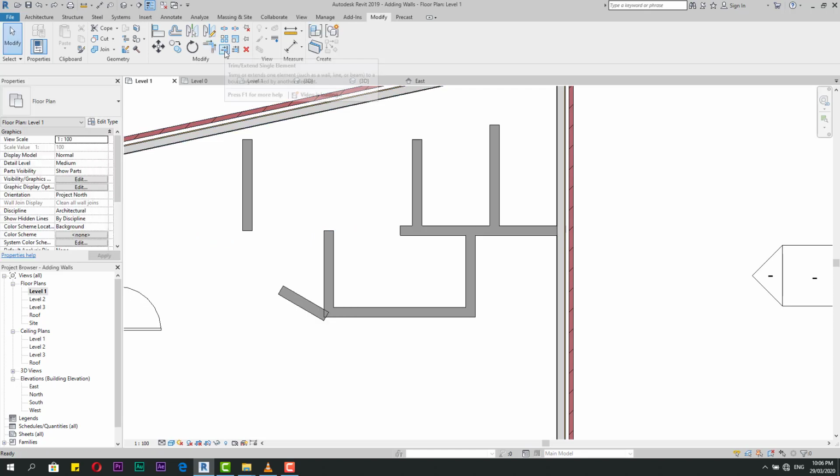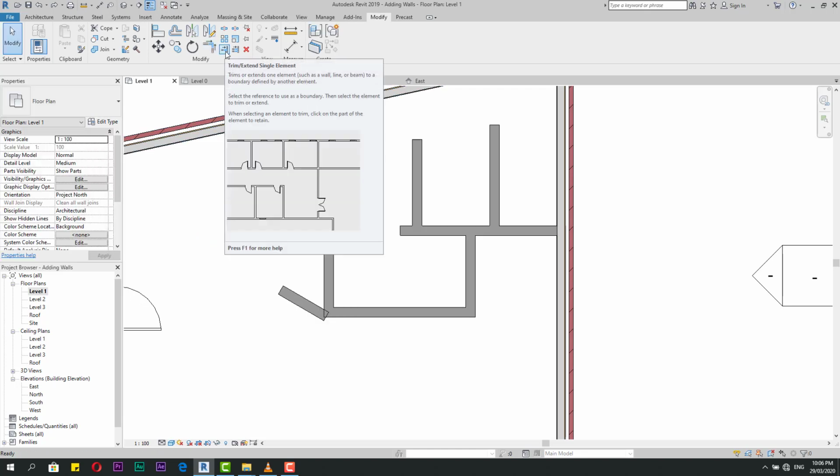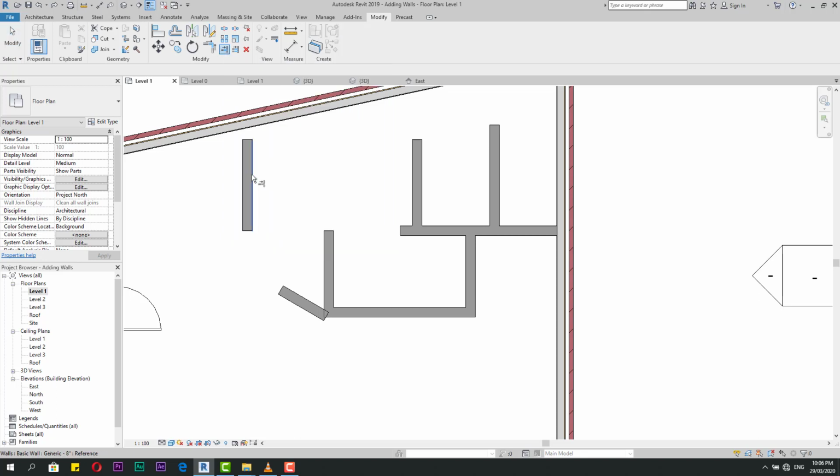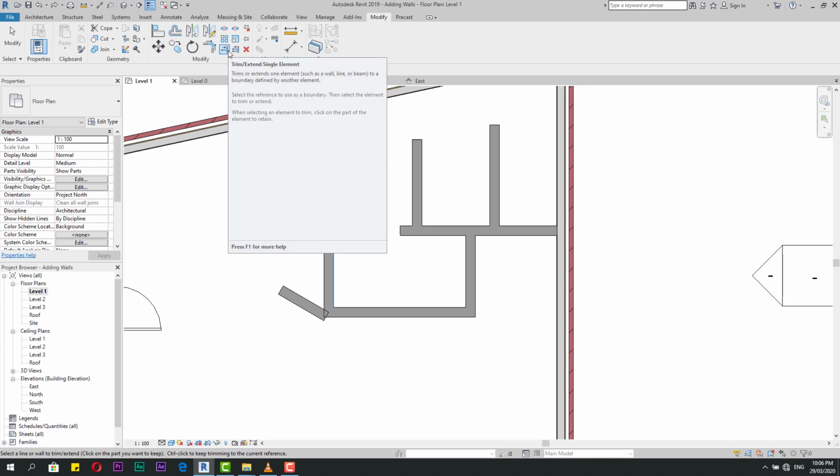Okay, the other thing we need to speak about is extend or trim. Just I click here. If I select this one as the reference and click here, take care what happens. It's similar to this corner, okay? With trim, I can make a reference for this. But the corner can make this shape, while trim cannot make this shape, because it needs a direct intersection, okay? If I have this, and I tell it this reference and I need this stretched to this, this is the meaning of extend or trim.